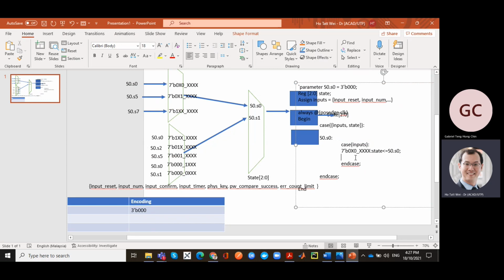So here this is state 0, so I can just list the second condition, just read it out. 0x1xxxx, then state goes to S0 to S5. Then here 7'b1xxxxxx state. Really easy to do. I'm done here for state 0.